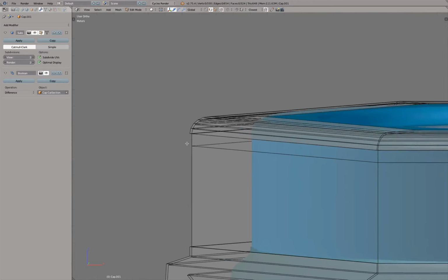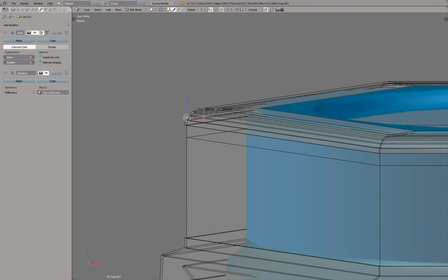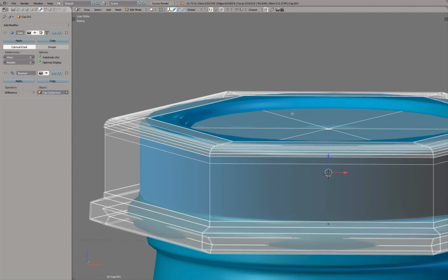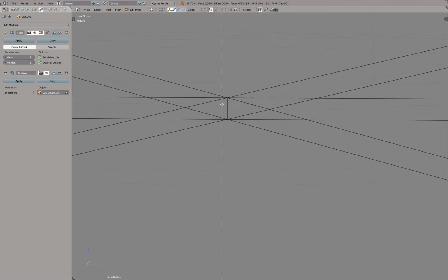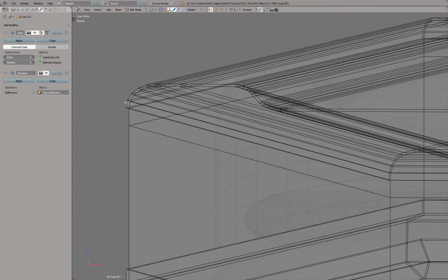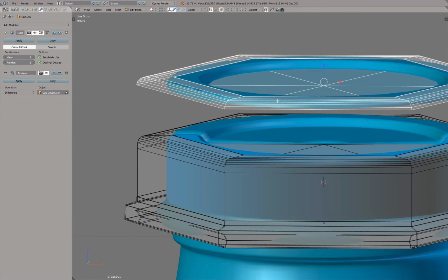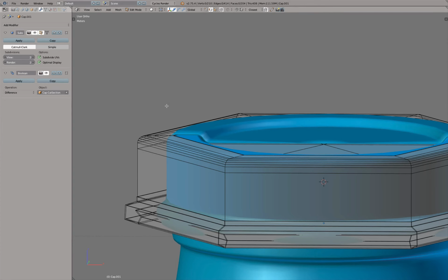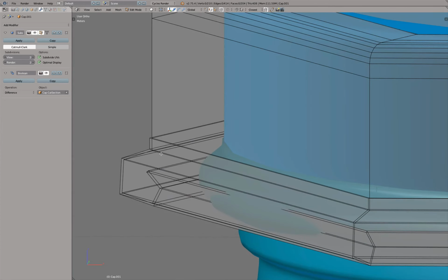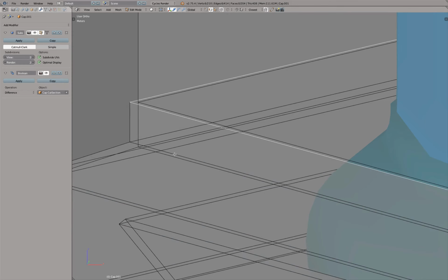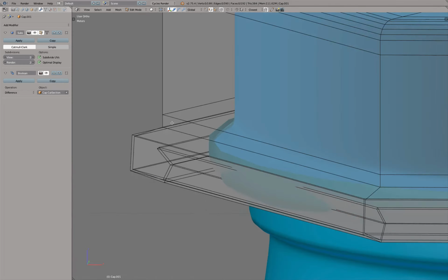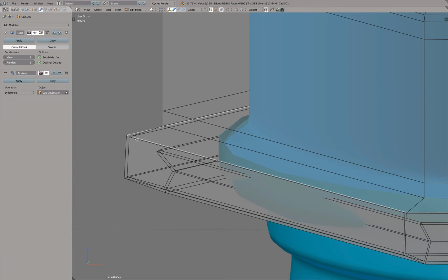And the main reason for that is, I think if I did everything right, I can select this one and press L with my mouse over it, and it's all selected. Why? Oh, I see why. There, this is connected. So we have to delete this, delete edges, not vertices, go to here, L. Now you see it only selected the top geometry, and that I can simply now delete. Zip, gone. And maybe this one and this one we delete.